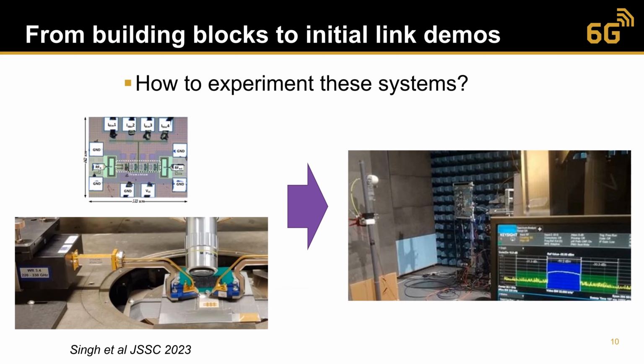The RF transceiver development starts from the IP block designs, where each main RF transceiver block is individually designed and tested. Sub-terahertz RF ASICs are tested at a probe station with waveguide probes connected to frequency extenders. The frequency extender expands the frequency support of the RF measurement instrument beyond the native operation of the equipment.